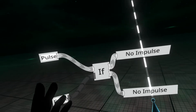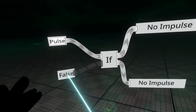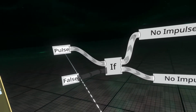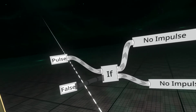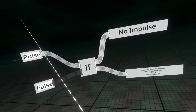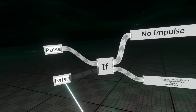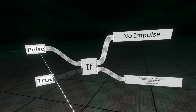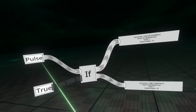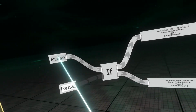So what the if node does is it will send an output to the top here if this condition is true, or an output to the bottom here if this input is false. So right now this input is false, and so if I start this if with a pulse, you'll see that we get an output to the bottom chain here. If I change this input to a true by clicking on the false once, so it says true, you'll now see that I will get an output up the top here. I can change this back to false, and we'll get an output over here.